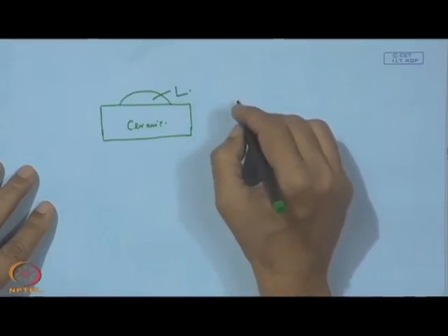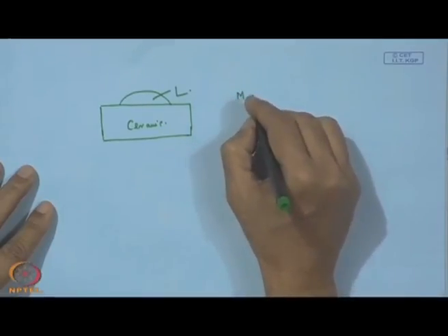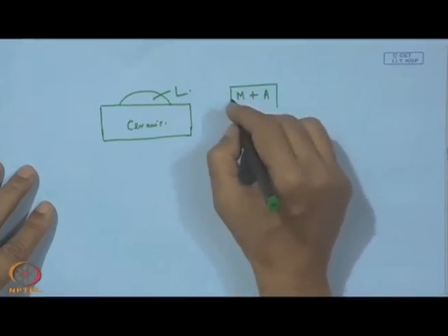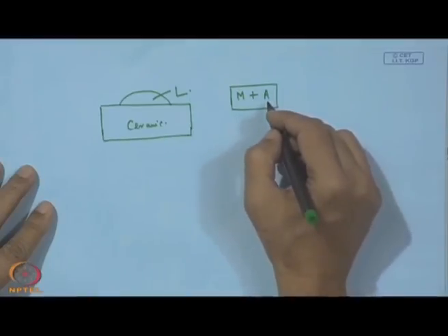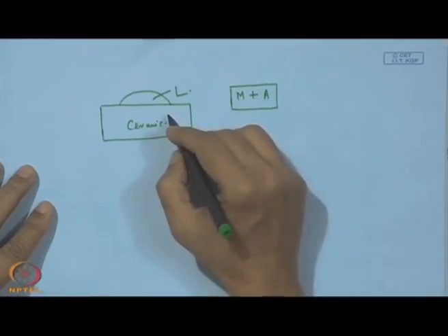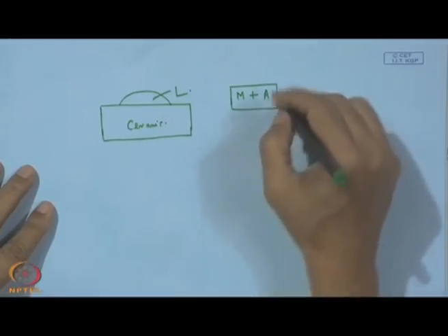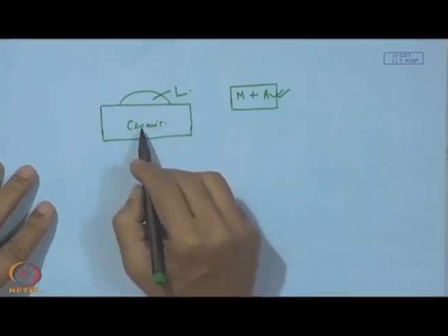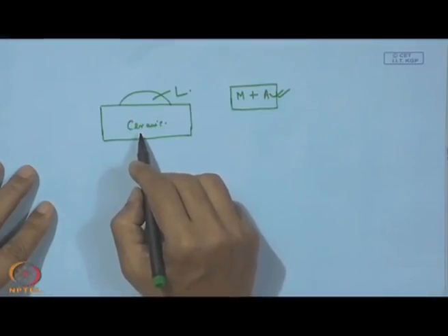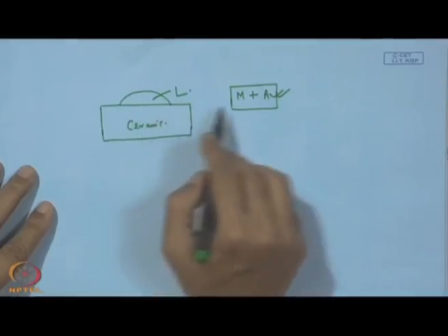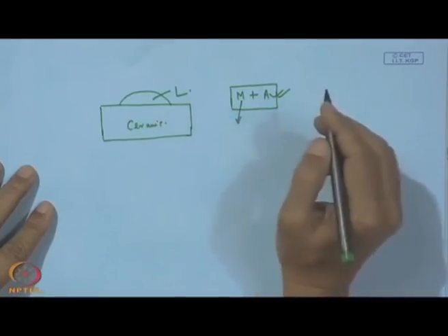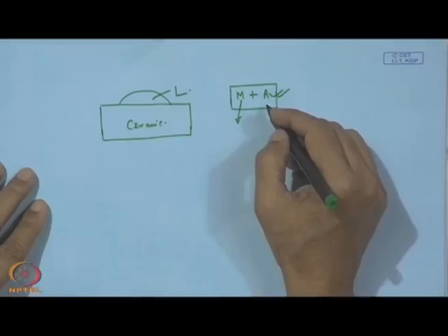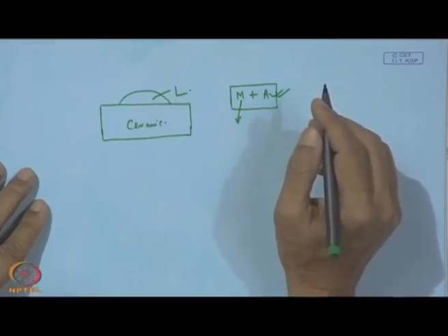must have some additive which can enhance the reactivity of this liquid over this ceramic, and as a result this additive will be segregated towards this surface and change the chemistry of the ceramic, making that surface wettable by the conventional metal M. So, this is also one of the very important aspects of metal-ceramic joining.